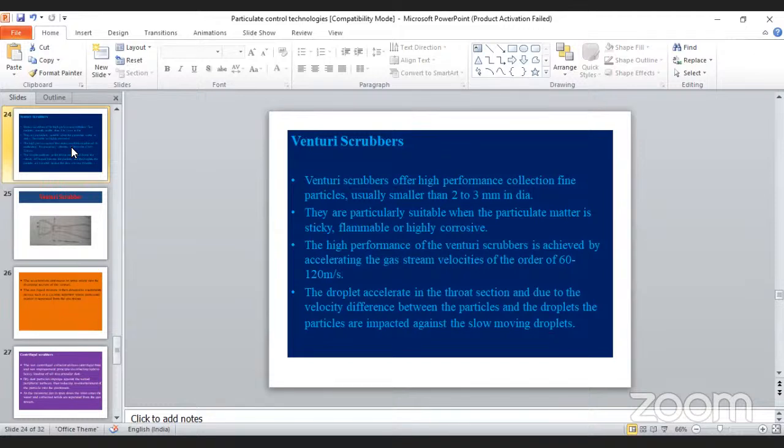Since it is gas, the gas flows fast, and the solid or liquid droplets will settle down at the side. But even then, in this particular case, not all of it is possible. Still, it may carry something. If we follow with the cyclone separator along with it, it will give better results, because highly toxic, corrosive, and flammable substances are present. Those substances will be separated by making use of the Venturi scrubber. The working principle of the Venturi scrubber is pressure difference, nothing else, or the pressure difference we are giving in terms of velocity difference.